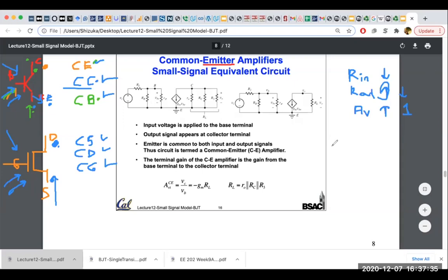For instance, you have a block here, and you have another block here, and for instance, this R out is so low. Well, you don't want to put a system that has a very big impedance here, R in, because then you won't be able to get maximum power transfer, right? Let's just draw this equivalent. You have a voltage source, you have an R out, which is, let's say, 1 mega ohm.